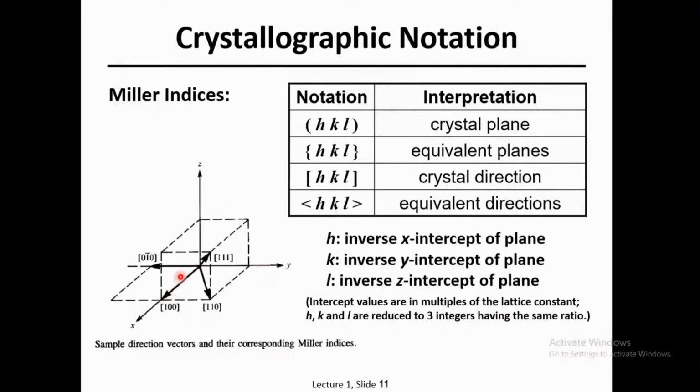So it's all along the X direction. And that's what we mean by the hkl, the crystal plane. So the crystal plane for silicon, then it's along, we said, the 100. So the Miller indices, here we have h is 1, k is 0, and l is 0. So this is what we mean by Miller indices.